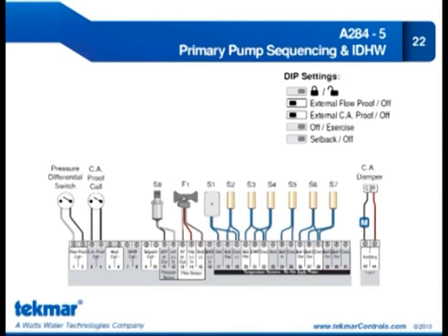Okay, I'm kind of mixing things here. Now you're referring to BAS, right? Well, I'm talking about we have a 2-temperature system now. We have one temperature that we're controlling to, and then we have another temperature that we can't see, but it's being blended by something. And we take one of those sensor inputs that we're not using for our 284, that might be 7. That would make it visible to the 284. Would that also make it visible to the BAS?